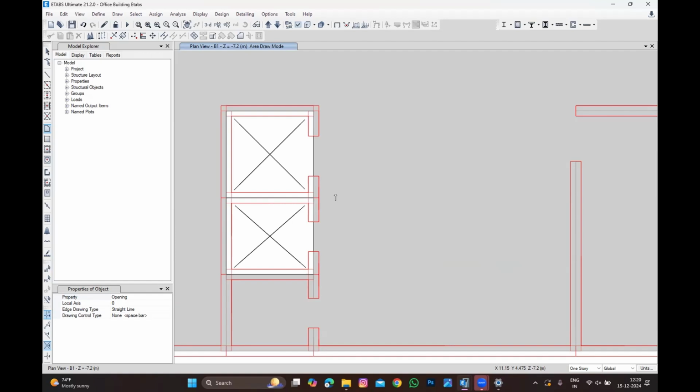Right. Step 2 is the diaphragm action. It will not give you that diaphragm action. It will give you only a sort of stiffness to the wall. I understand your concern, because the waist slab is not connected to the lengthy wall, so it will not provide this stiffness. That's what I was saying. The waist slab is connected to opposite sides, and it will transfer the load. But even if it is not connected, the wall tends to bend, and this will be the support.